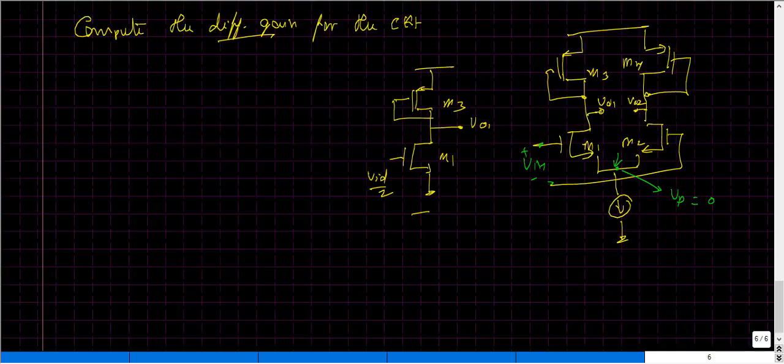And we know what the gain expression is. So what is that? The capital GM of this particular circuit is equal to GM1. It's not approximated, it's actually equal to GM1, and the output impedance could be found just by shorting the input to the ground and then looking up, which leads to a particular value, which is 1 upon GM3 in parallel with RO3, and when we look down through the drain terminal, the impedance would be RO1.